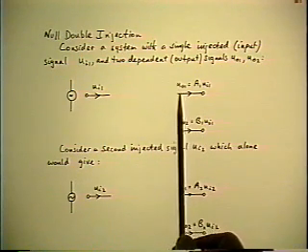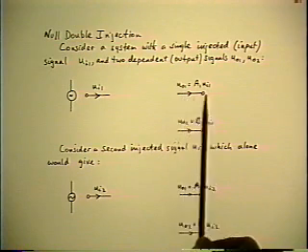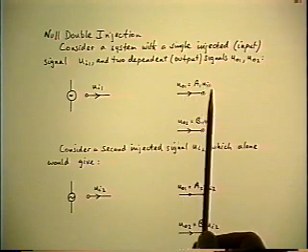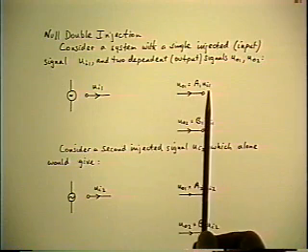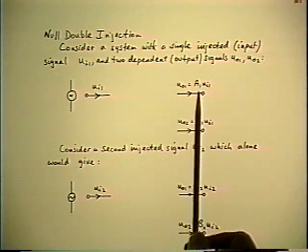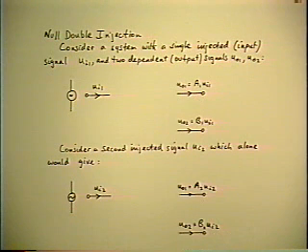So it's a U sub O1. And the only thing that I can say about it is it's proportional to the independent input, and the proportionality factor is something I'm going to call A1. A1 is a constant if the system is linear. Constant in the sense that it does not depend on the signal amplitude, although of course it may be a function of frequency.